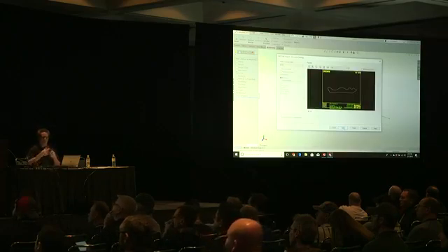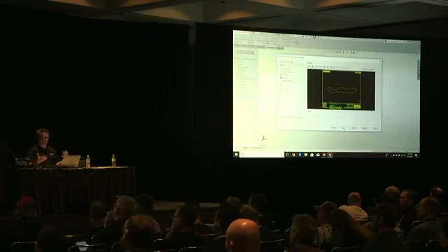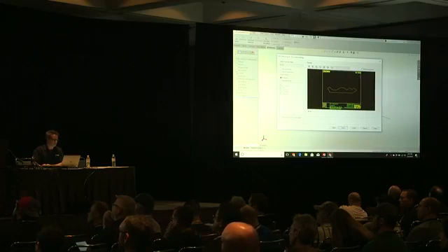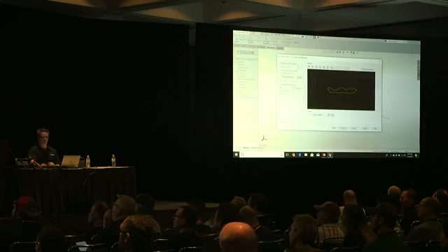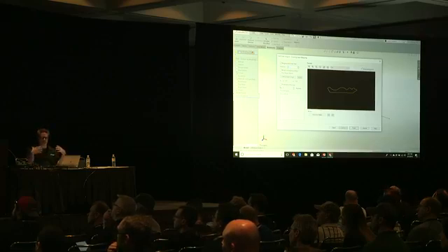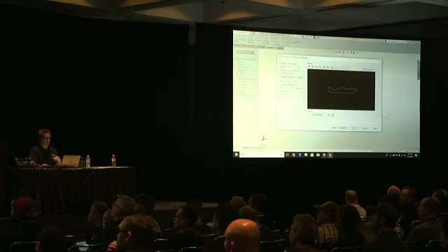And I want to wrap it around my room, so I'm going to do it as a weldment because that's a whole lot easier. First thing I'm going to do is be really picky about the layers because I just want that crown molding, so I'm going to turn off everything I don't need. And then because I cheated and looked ahead, I knew that they were really sloppy about their modeling. So I'm going to clean up a little bit of that by increasing this. It's just going to merge the points. It's not a pretty file.